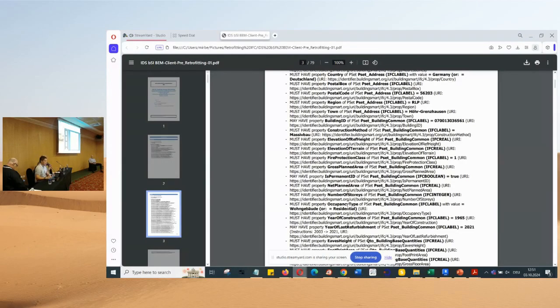Properties, actually, are flexible. The difference between classes and properties is that classes will be difficult to map. You need to know what the class is in IFC2x3, and whether it's the same in IFC4. If not, then you have to change and add an additional type, or facet in that case. Here we have a door, for whatever. So you can adjust everything according to every standard, like a standard schema.